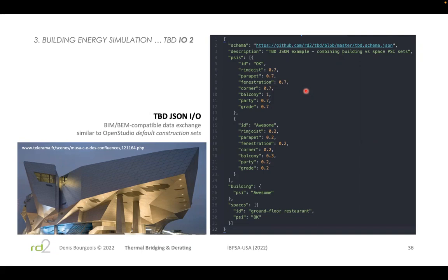So it is possible to isolate an individual edge and say, this is not a minor transition between a minor angle difference between the azimuth of two walls that connect to each other. This is actually an expansion joint, a structural expansion joint, and there is a thermal bridging value associated to that. Here's the way to target that specific edge. So that input file is very critical.